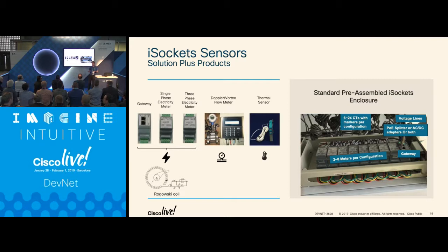So we are measuring the delta of temperature between input and output, quantity of water that goes through the cooling system, and then we can calculate the BTU of the cooling system, and then its efficiency, because we also measure power usage. So you have BTU, power usage, and then you can measure efficiency of systems like that. Okay, this is a box with all different sensors and one gateway all together. This is really how it looks like when this is finished. All right?